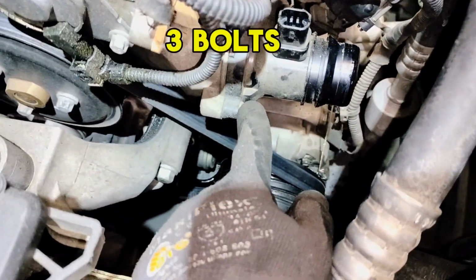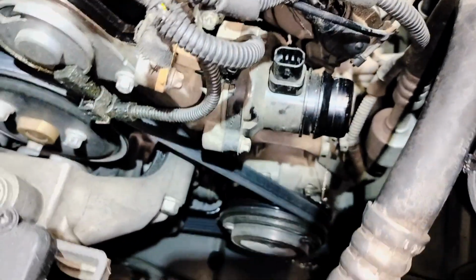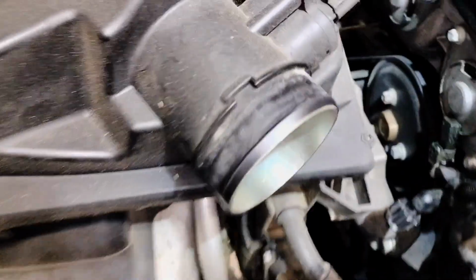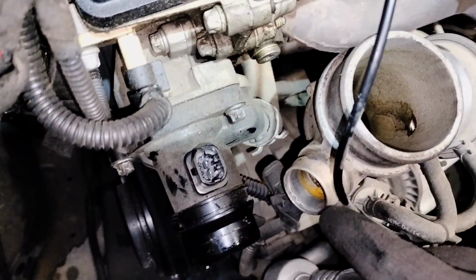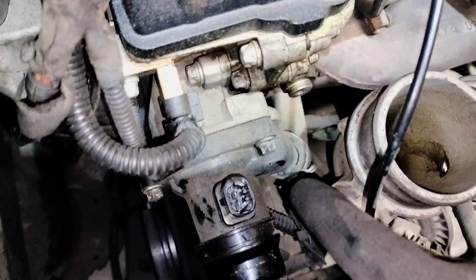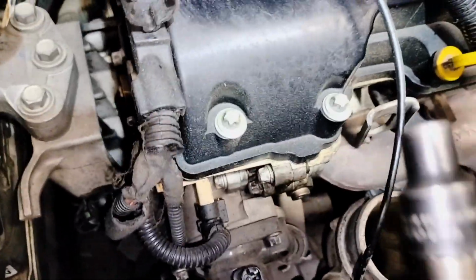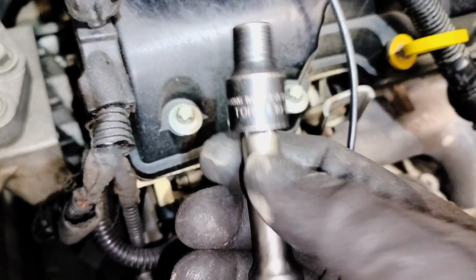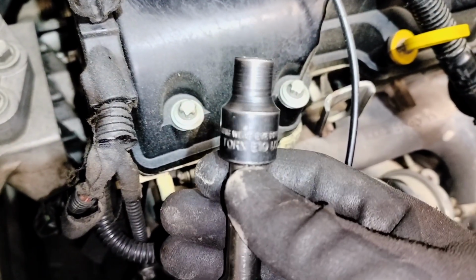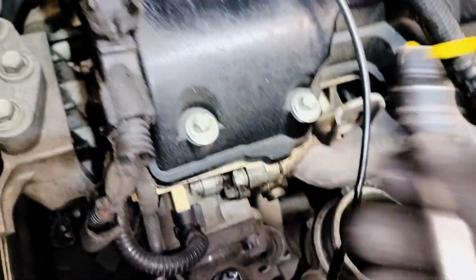So now it's time to remove these two bolts, and then last we're gonna remove a hose clamp that's on the other side. And if you want to remove this hose, it's necessary to remove these throttle body hose as well here on the side in order to get to your bolts here. What you're gonna need is a Torx socket. This is a Torx E10 in order to remove it.